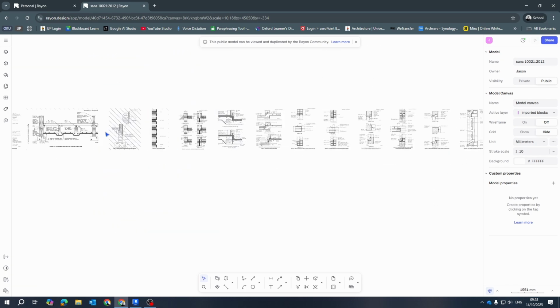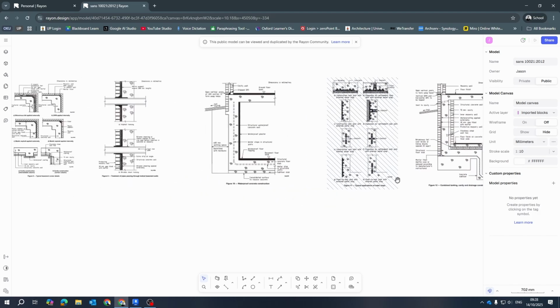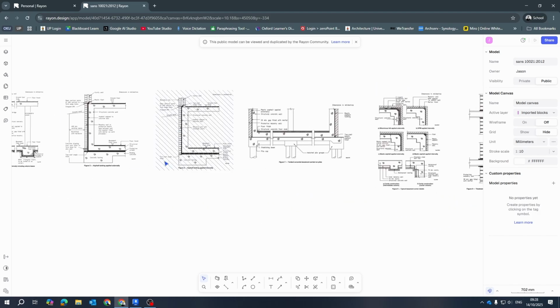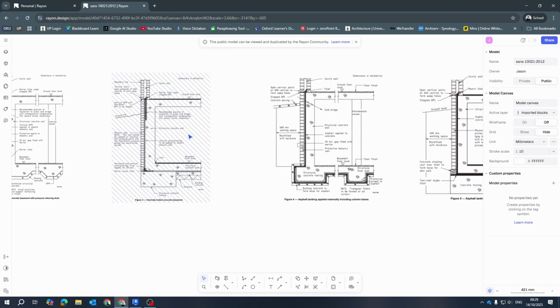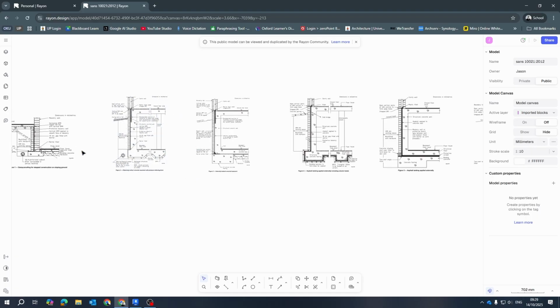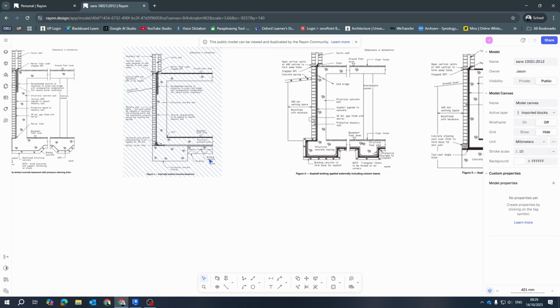You see we've got thresholds when we come into our building. We'll look at that now. But for our basements, you can see typically we're going to use these types. I'll probably use this type of arrangement for my basement. I've got a concrete wall, so I can just use, but that 100 mil is basically where the steel sheets will come down. So basically this is the type of detail that I'll probably use, minus the brickwork, because I've got a concrete wall going up. Okay, so just have a look at these, how they work, these details.